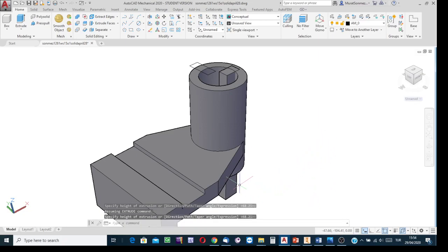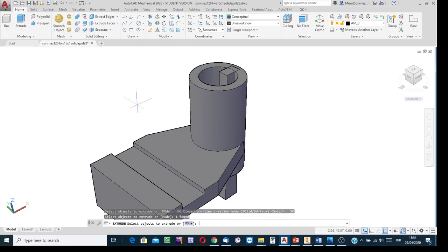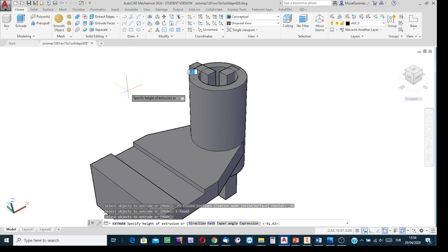I further extended this rectangle to be able to much more easily indicate it at the subtraction stage. Then apply the extrusion process: indicate this rectangle as the profile, press enter, and create this rectangular prism, not arbitrarily. Its height must be equal to 7 because 7 is the height of the empty space.